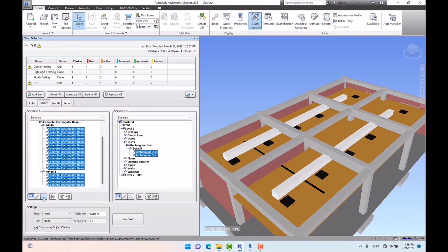And the next one is points, which includes point geometry in the clash test. Same as lines, points are exported from AutoCAD too. But note that points and lines are not transferred from Revit to Navisworks, only the geometry of your objects is going to be exported to Navisworks, but the points and lines never. So selecting points and lines is not necessary. And about self-intersect: self-intersect tests the selected geometry against itself for clashes. Actually this is used for geometries or objects which have intersections with themselves, for example stirrups. And we do not consider self-intersections as a clash, so these elements are not going to be checked in the clash detection test.